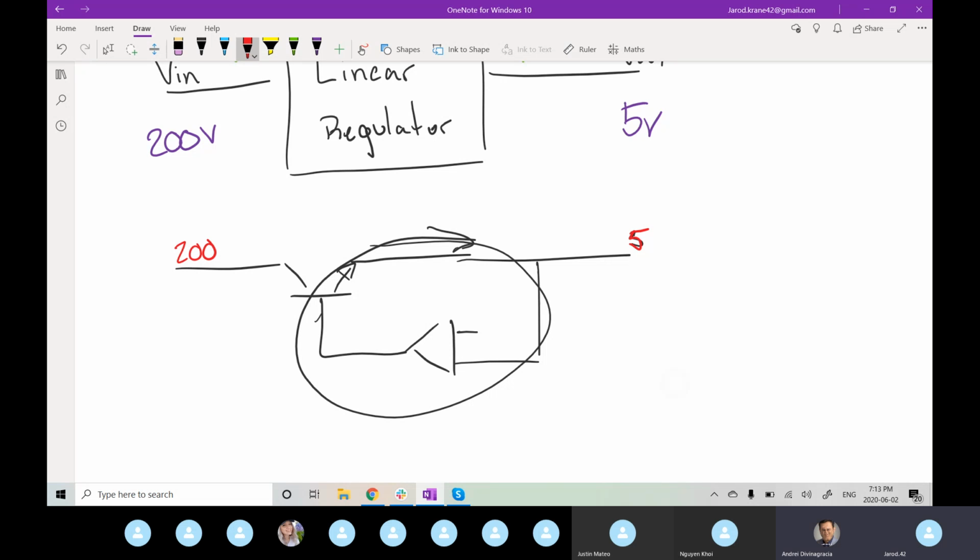So in the resistors that actually step it down, and just in general through the system, you'll have a lot of power losses due to heat. So this becomes a lot less efficient, purely because you just start burning through power, because it's got to go somewhere to drop 200 down to 5.